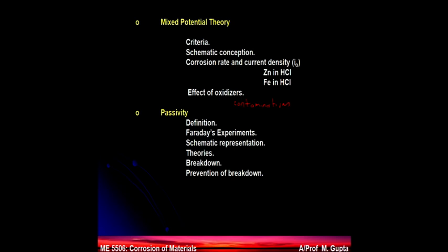So if you are invoking the principle of passive behavior of a material, you also have to ensure that the environment in which you are putting it does not have the destroying elements. Like normal traditional stainless steel, we cannot put in the marine application because the chlorine can damage the oxide layer and the corrosion can start there. So that is what basically in essence we learned from the concept of passivity.